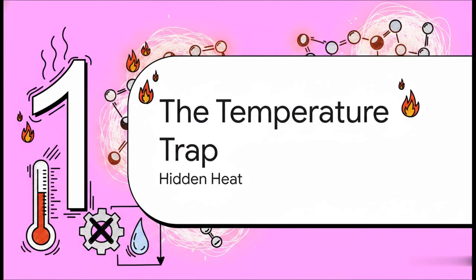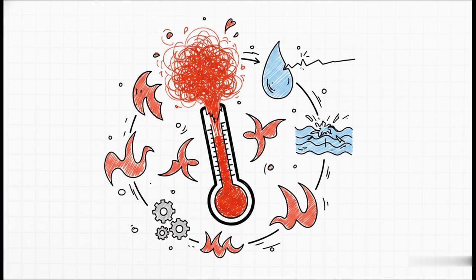All right, section 1, the hidden temperature trap. When you're grinding pigment, that immense mechanical energy is drastically altering the thermodynamic reality of your slurry, right in real time. We are not talking about a cute 1 or 2 degree shift here. In high-intensity milling, we're seeing temperature spikes that can easily hit 30 to 40 degrees Celsius above your baseline. No way is that just background noise. That is a massive thermodynamic shift that hits your viscosity and surface tension directly. It literally penetrates every single stage of your process.